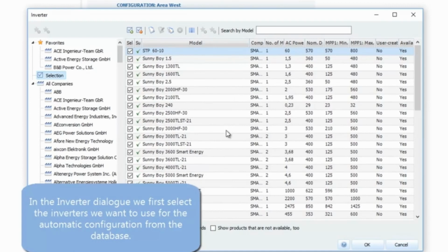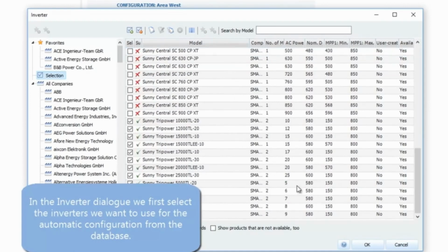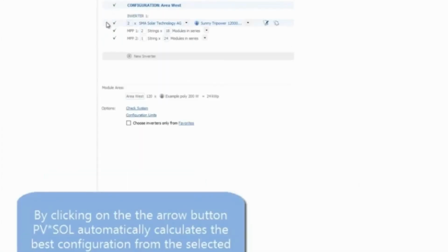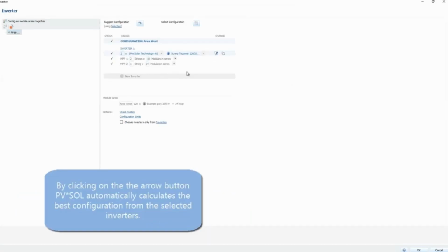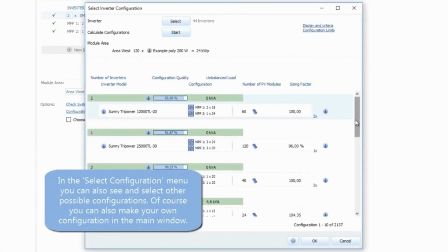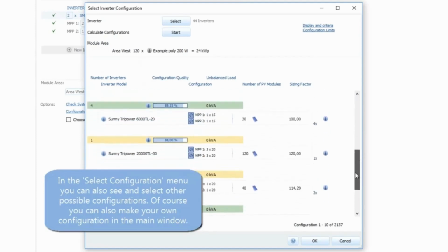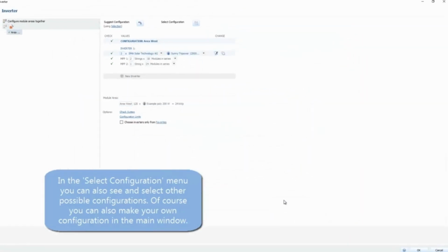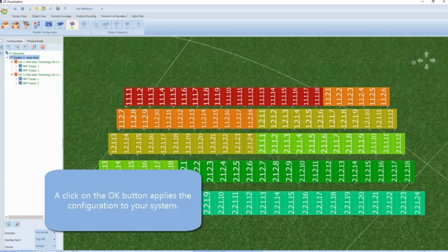So this is also to be decided for the modules, but the inverters are also quite relevant. You can use one central inverter, but it is most preferable, especially if you have shadows, to use multiple inverters. The most extreme would be the module inverter, so each module would have a separate inverter. But in this case, they use string inverters for every row. You have one inverter, and each string will operate separately. So you can choose to take a look at the different range of maximum power point tracking capabilities.